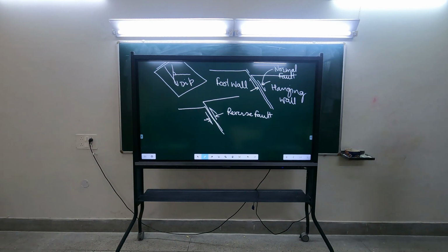In which case do you have to apply more force? Pushing. Why? We have to work against the gravity. Why work against the gravity? The gravity is the same in both cases, whether you are pulling or pushing. The friction in pushing is more. Why is the friction more in pushing? Because the component of the pushing force applies additional normal force. When you are pushing, your force is in the downward direction, so it has a component vertically downward, which adds to the gravity, and hence the friction force is more.